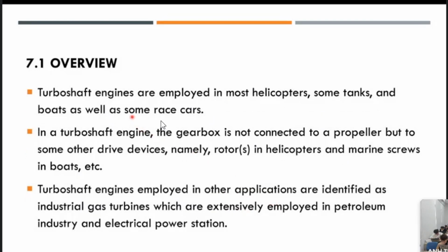The turboshaft engines are normally employed in most helicopters, and some are also installed in tanks as well as boats, and some also in race cars. In a turboshaft engine, the gearbox is not connected to a propeller, but to some other drive devices, namely rotors in helicopters as well as marine screws in boats.